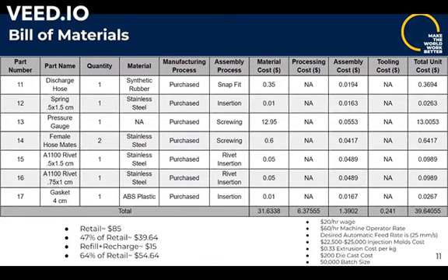And some assumptions for filling out this bill of materials. We assumed a $20 an hour wage, $60 an hour machine operating cost, an automatic feed rate of 25 millimeters a second, and then an injection mold cost of $22,500 to $25,000, 33-cent extrusion cost per kilogram, $200 die cast cost, and a 50,000 batch size.